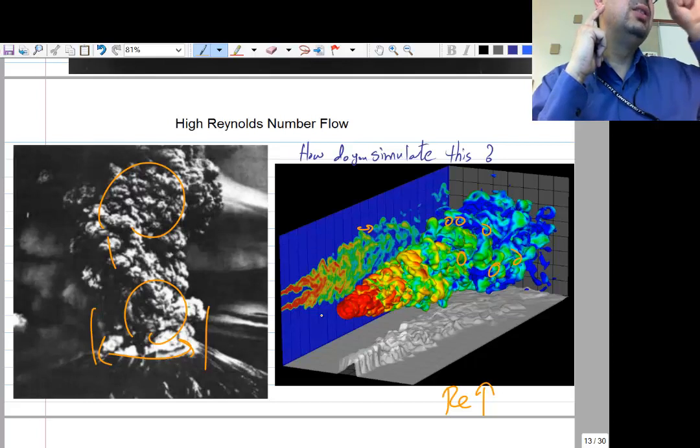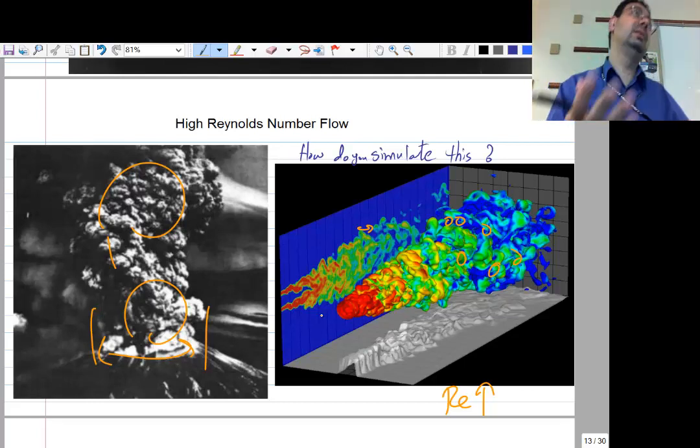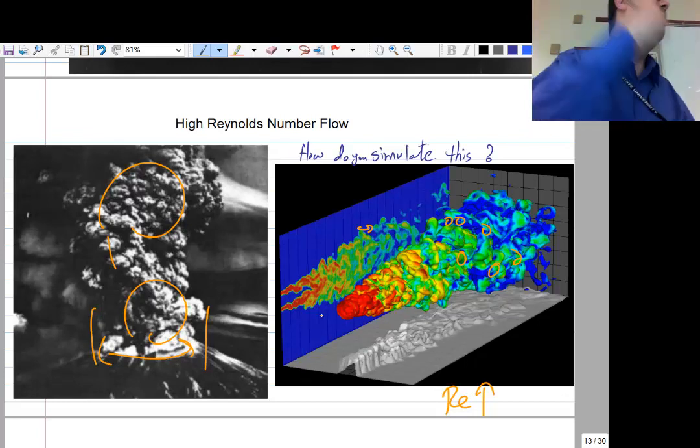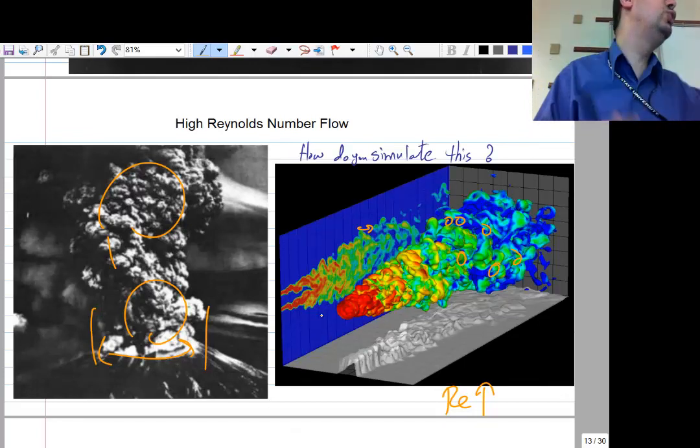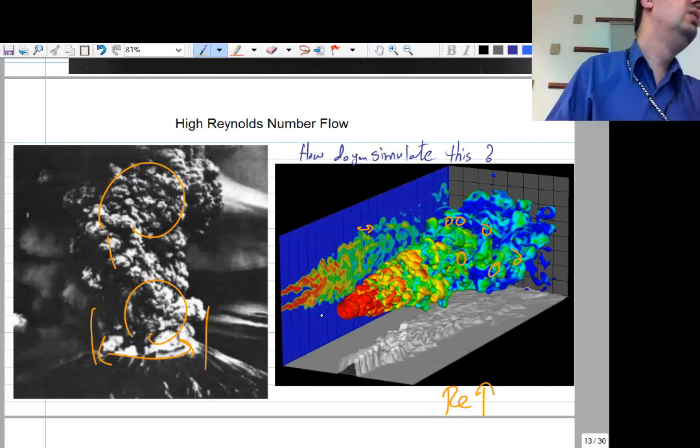When that distance is so small, the shear rate, partial U, partial Y, is very big. And therefore, the shear stress that will be generated out of it will be really huge. The viscosity will kill it, basically. The resistance is really huge for something with such a high shear rate. If the gradient is really high, that means the shear stress is really high. That means it takes a lot of energy to sustain those guys and keep them rolling.